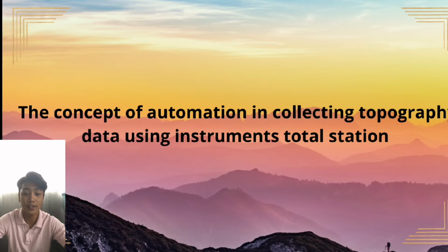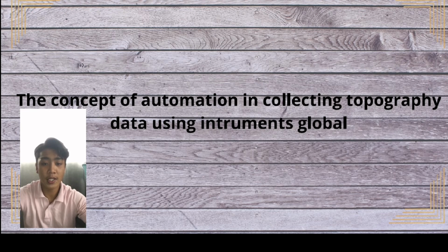Third, instrument height, reflector height, and minimum height, bearing and distance of data are all required to be kept in the total station memory. For concept of automation in collecting topography data using instrument global.